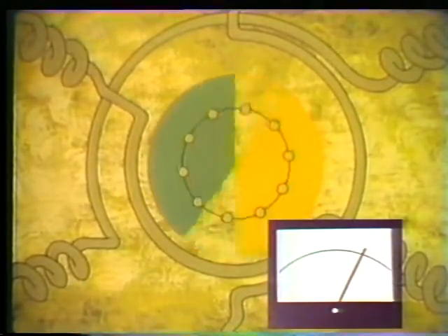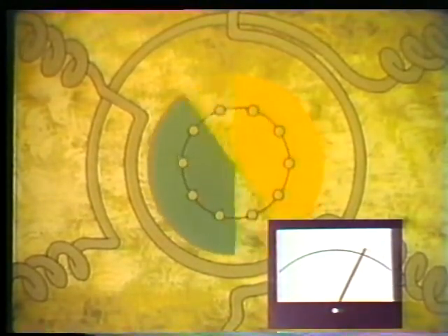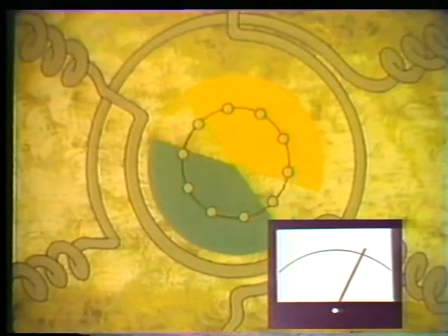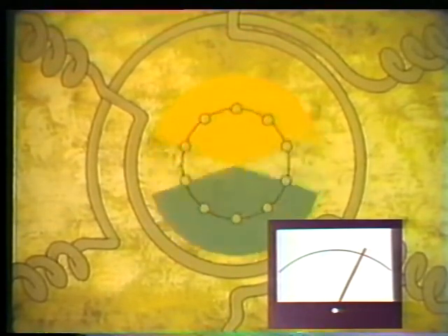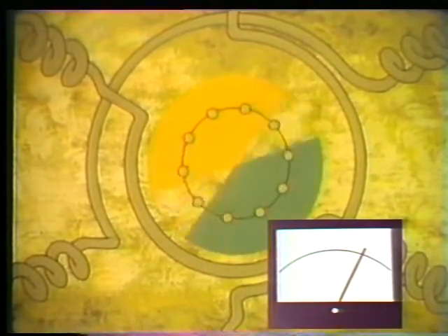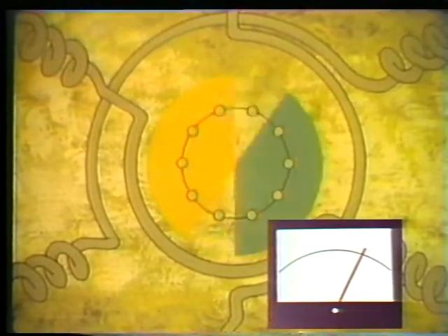At the same time, there's an increase in the amount of voltage induced in the stator. This increase in voltage causes current flow to go up, and the electrical power that the motor is using also increases.